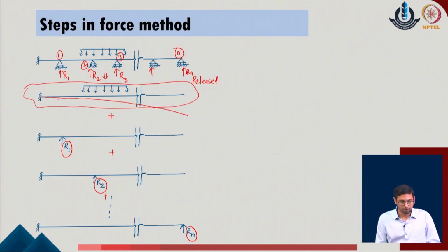At the position of the 1, we will have some amount of displacement which we call as displacement at the position 1 due to the external load. Now, with the same system, I can calculate the deflection at the point 2 and I can call it the deflection at the point 2 due to the external load. Similarly, I can keep on doing this for all the n number of points and I can define displacement at the position n with respect to the external load of the given system.